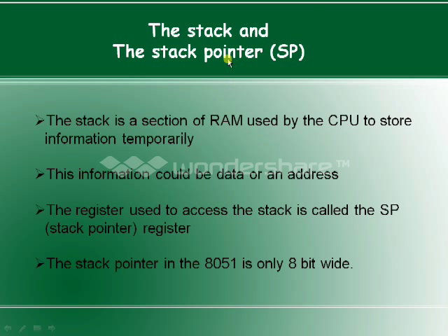Now we'll discuss the stack and the stack pointer. The stack is a portion of RAM which is mainly used for holding some temporary information like data, or it might be an address. The stack pointer is again a register, similar to the program counter as well as the data pointer, but this time the stack pointer is going to hold the address of the stack locations.